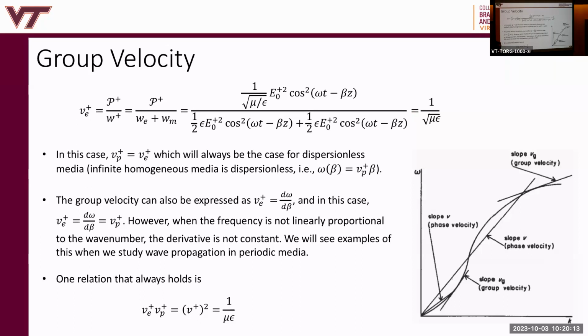What is dispersion, right? Dispersion tells you that the wave number of the medium could be dependent on the frequency. Think of a rectangular waveguide. We haven't studied rectangular waveguides yet, but in rectangular waveguides, the longitudinal wave number could be a function of the frequency. If I choose a particular frequency of operation, then I would get a mode from that particular frequency that has a particular beta in the direction of propagation. So it's beta as a function of omega.